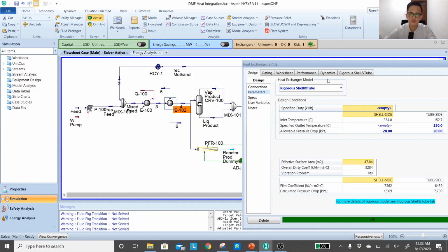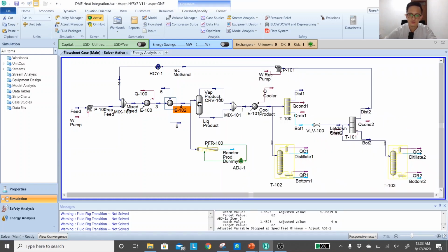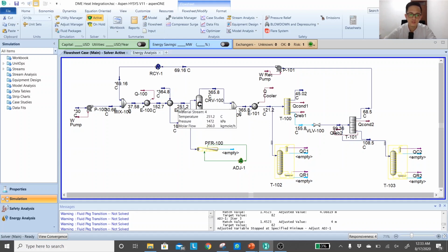Okay, you can accept the design, and then you will notice that everything looks good in the heat exchanger part. Something is wrong and has to be fixed in the distillation, but at least in the heat exchanger it looks good. And you will notice that the temperature changes. Okay, why? Because the area provided is even bigger than our initial calculation. They have 1% excess. That allows the heating process to continue, so that the temperature will start to increase.